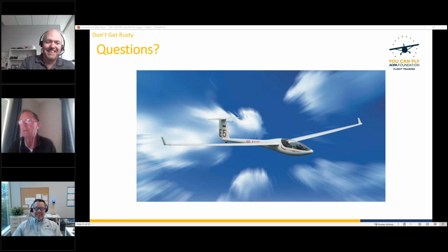Yeah, and that's just because it's relatively safe to do it. You can let a student do it at 200 feet. If you were highly proficient, you could do it at less than that. But yeah, it's pretty amazing. But again, it's all a function of knowing what your aircraft is capable of. So the impossible turn will vary with the aircraft.